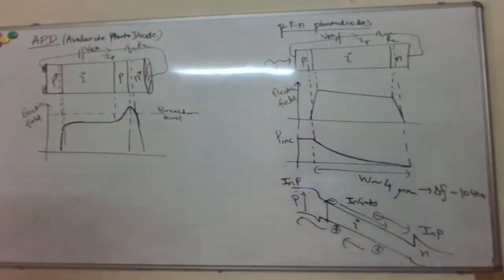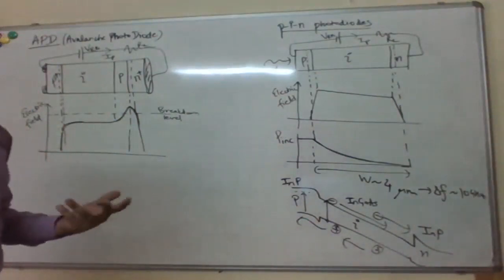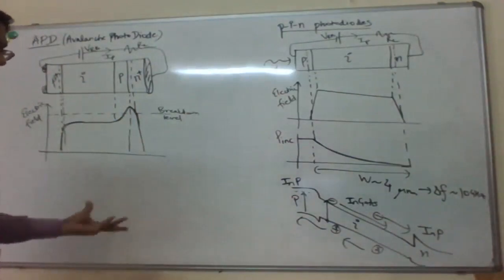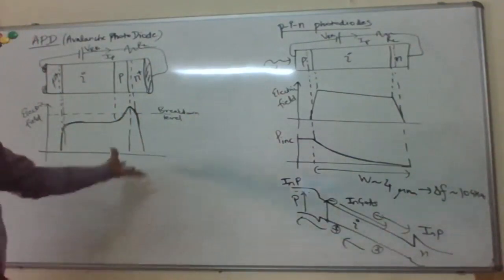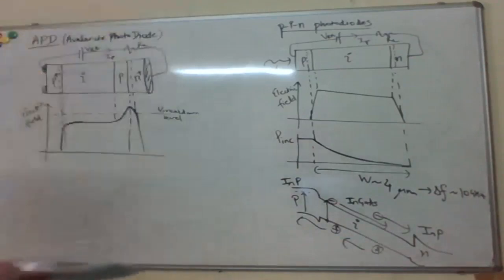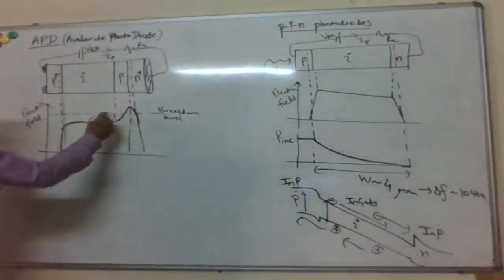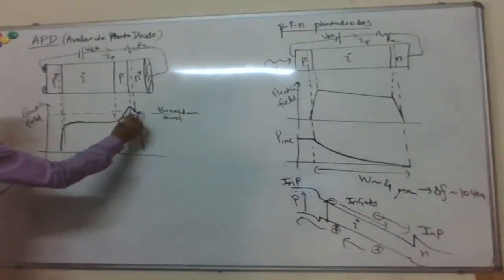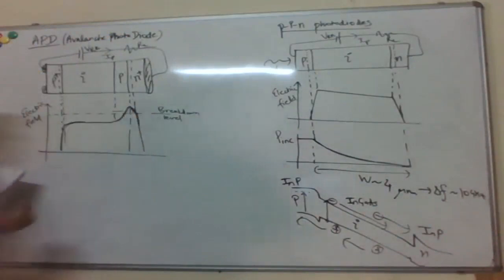Okay, you cross this threshold, so this analogy of this snowball now just picking up more and more snow as it rolls down to become a giant mass. So basically, the electrons and holes which are in this region where the electric field is higher than the breakdown region,